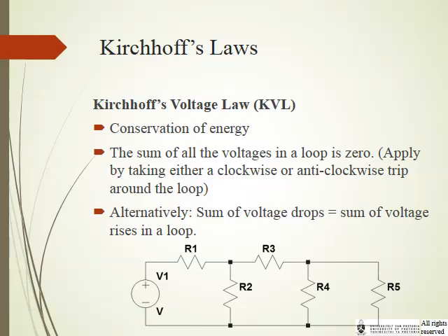The other Kirchhoff's law is Kirchhoff's voltage loop law. Here it also works on the basis of conservation of energy, not conservation of charge, as Kirchhoff's current law does. So here we've got the sum of all the voltages in a loop is 0. So we can go either clockwise or counterclockwise in any of the loops.